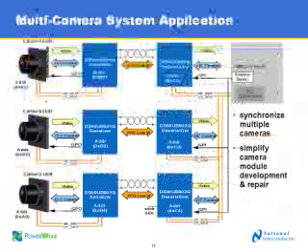First is the common I2C bus, and you'll see that connected from the microcontroller to all 3 of the deserializers. And the unique thing here is that everything is independently addressable. So as we mentioned earlier, both the serializers and deserializers have programmable addresses. There's a single pin that can be controlled via resistor network to select one of seven unique addresses. This means you can have 7 different serializers, 7 deserializers in a system, and all of them can be addressed independently by the microcontroller.